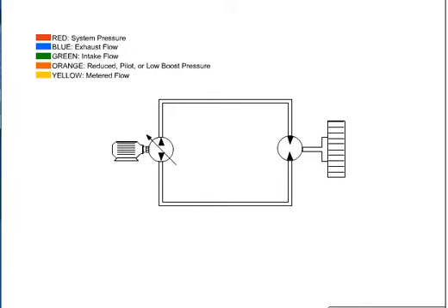This first circuit is a basic system with a bidirectional variable displacement piston pump and a bidirectional hydraulic motor. When the pump is on, stroke flow is directed to the hydraulic motor, giving it rotation. Rotation of the hydraulic motor is reversed when the piston pump swash plate goes over center. Controlling the output speed from the hydraulic motor is achieved by varying the output flow from the variable piston pump. If the pump is not rotating or is off stroke, the hydraulic motor will not turn.